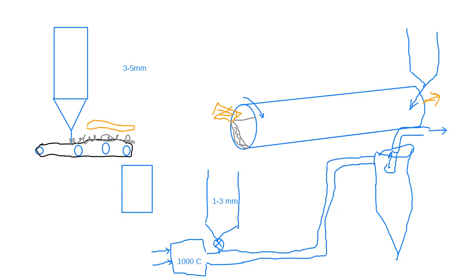Curved pipe would be a better description. That is a curved pipe that goes around, because you're going to get erosion on the outer edge, where the particles are pushed against the steel, whatever your construction material is, and therefore you will always get erosion as soon as there's a bend.